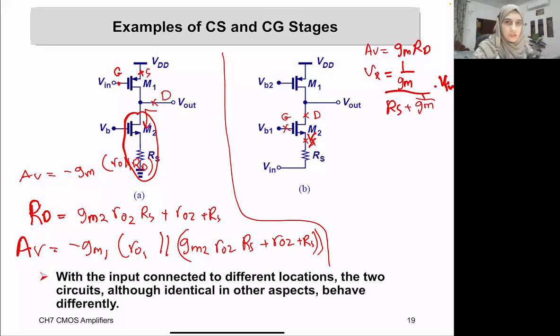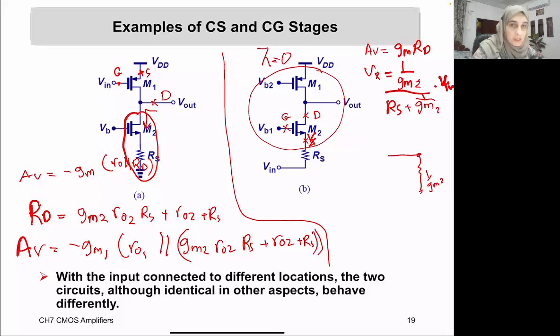And from where do we reach this conclusion? If you remember, we replace the entire amplifier. Here we must assume that lambda equals 0. We will have 1 over GM2, our input impedance of the amplifier. So we replace the entire amplifier with its input impedance, and we have the value of RS here, the resistor, and the source Vn. And we're trying to find Vx here.